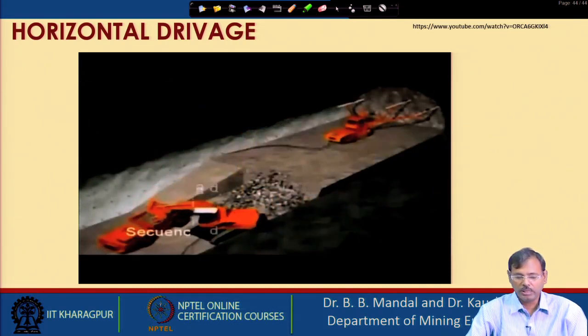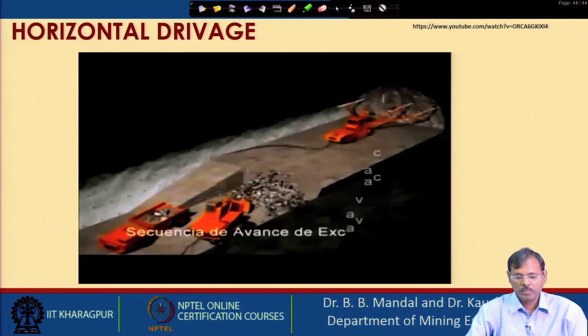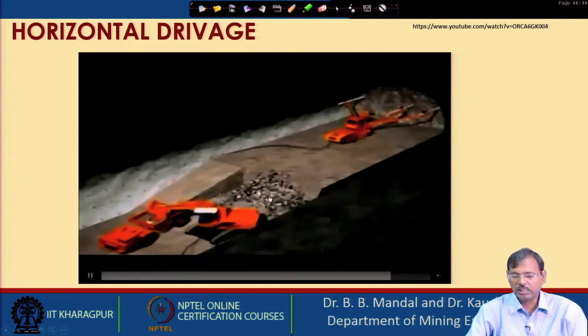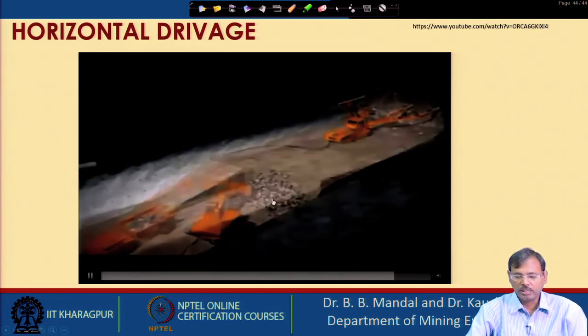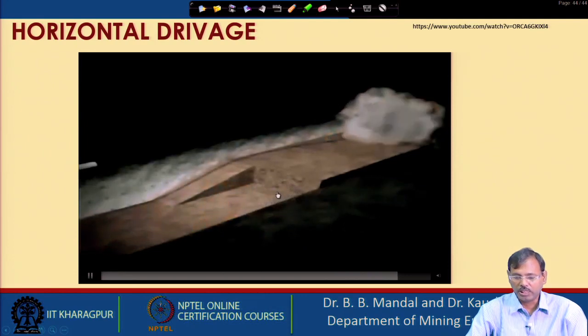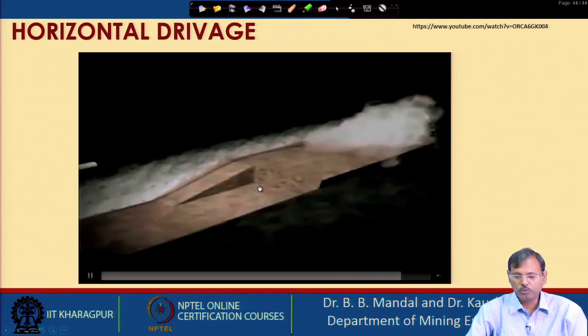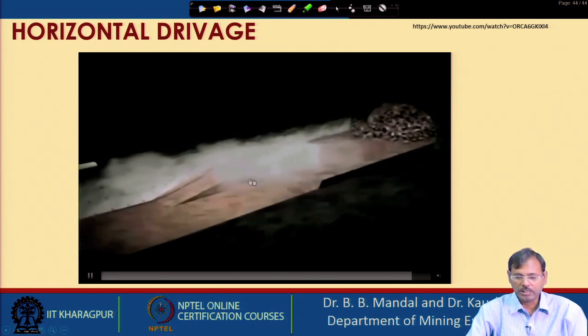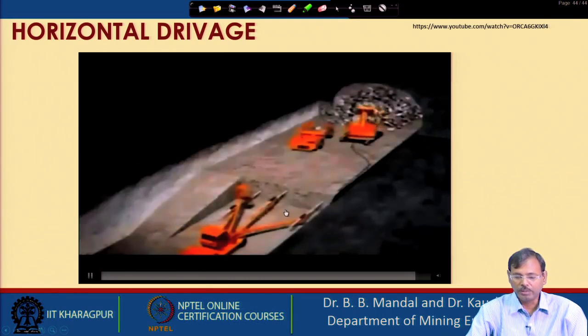Though in mining in general we use this, another feature which is in general used for a tunnel drift or tunnels of large dimension is where two phase working is carried out. One is the front phase and in the second phase the heightening of the tunnel is carried out by the benching method.